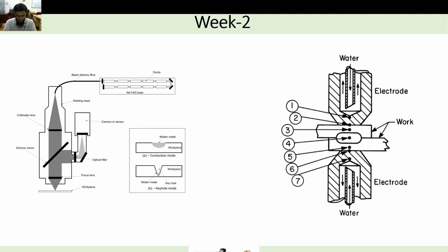So, coming to the welding process that we use in the automotive industry. As we know, our aim is to minimize the weight and maximize the strength, so that by minimizing weight, the fuel consumption and CO2 emission are low, and by maximizing the strength, we get crash resistance. If we get an accident, the car should be able to sustain that sudden impact. So for that we are aiming to get high strength in a very thin sheet of a car body.